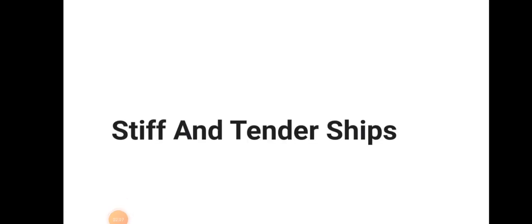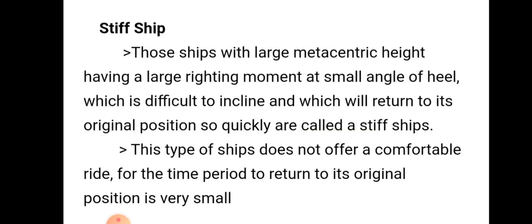Stiff and tender ship. The other two types of ship are stiff ship and tender ship. Stiff ships are ships with a large metacentric height. They have a large righting moment at a small angle of heel, which makes them difficult to incline, and they will return to their original position so quickly. They are known as stiff ships.